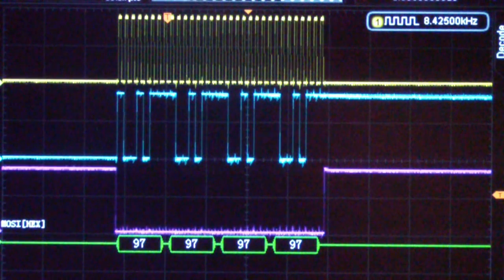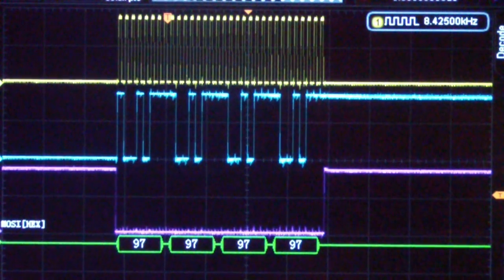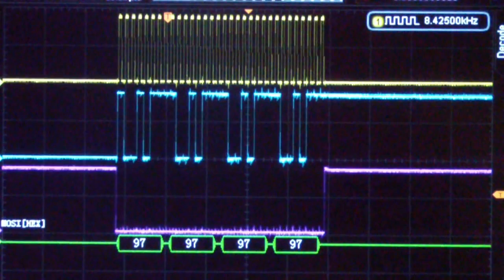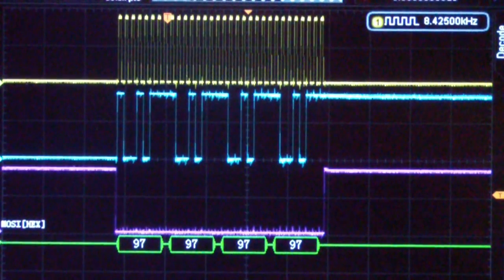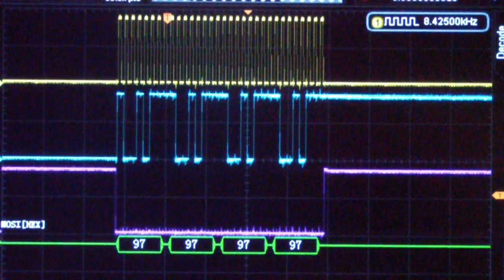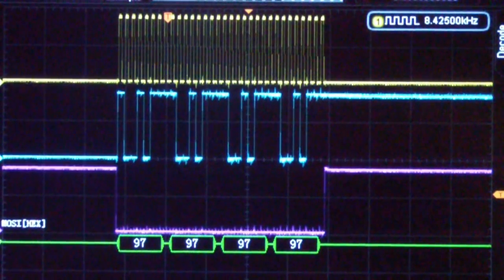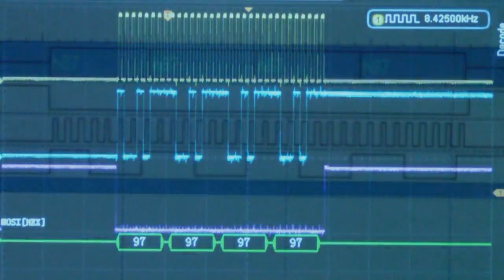that is the slave's response to the master, on the same scope screen. And so the bottom line of all this is, in my opinion, if you don't have at least 4 channels available to you, it's really kind of pointless to think that you're going to be able to do any serious SPI decoding. So let me stop at this point and then show you the same thing on the Analog Discovery, which is in essence a 16-channel logic analyzer.